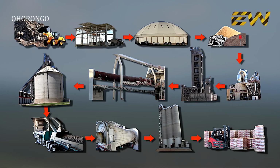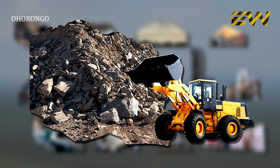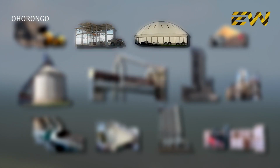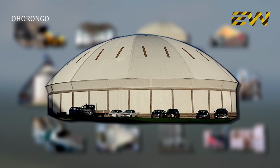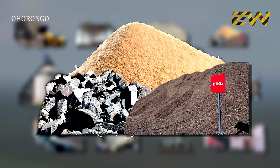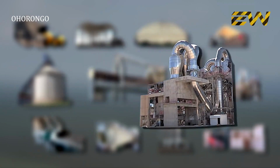Now let's summarize the entire cement production process. This is a schematic presentation of the whole cement manufacturing process. Raw materials such as limestone, shale, and marl are collected at the quarry and transported to the crusher. From here, it's conveyed to the mixing bay where it's mixed to a homogeneous material. Additives such as high-grade limestone, sand, and iron ore are added and then conveyed to the raw mill where it's dried and ground to a fine powder.